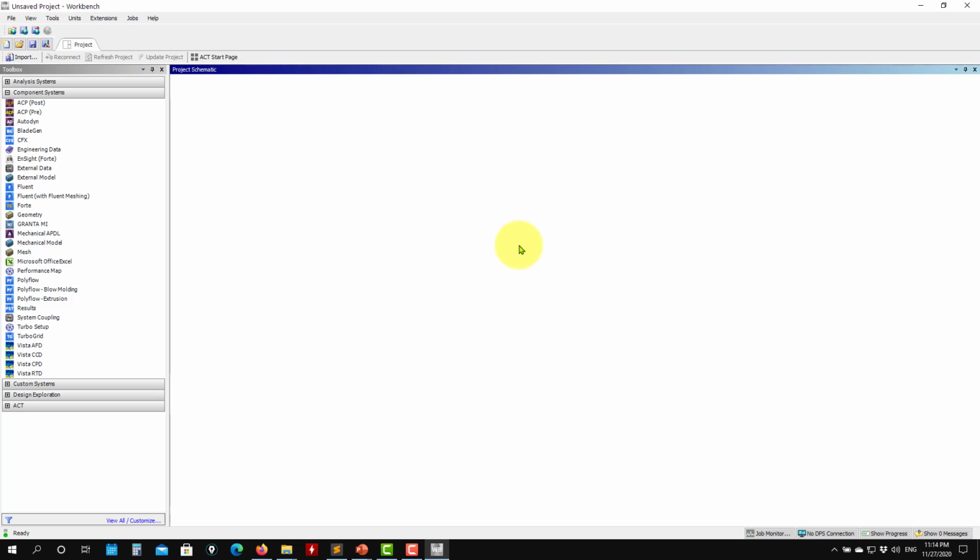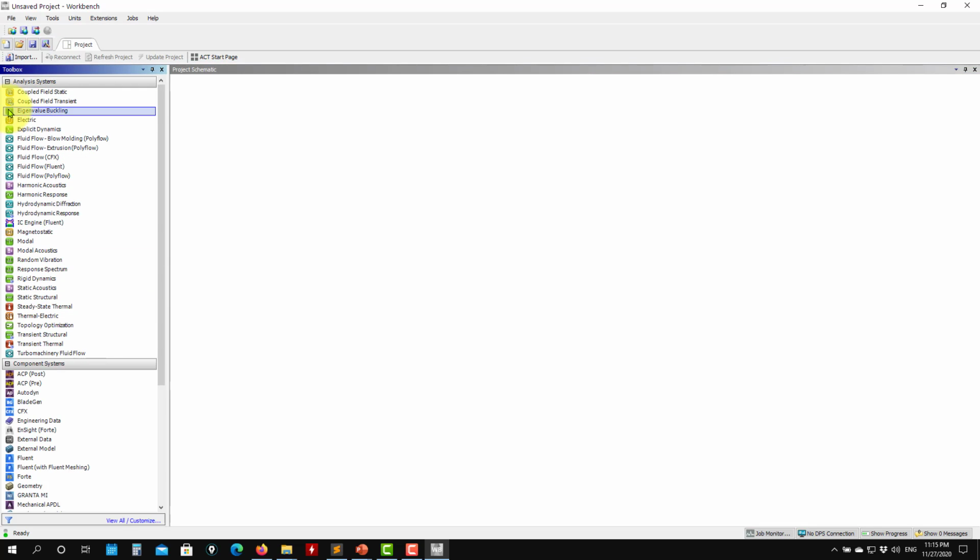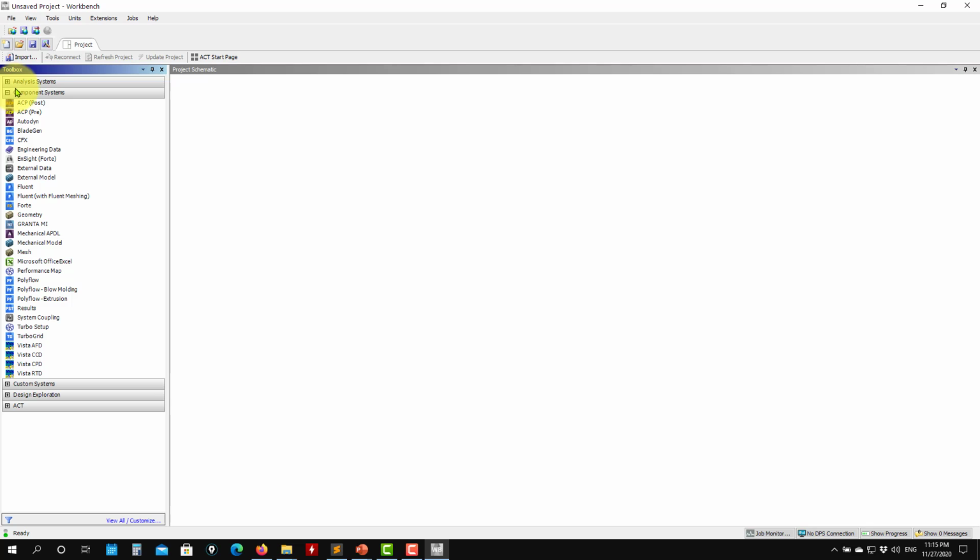So you're going to get this window. Here you have all the applications that come with Ansys. We're focusing on CFD here. You also have structural dynamics, a lot of stuff inside, but we want to focus on CFD. So the workflow in CFD is to generate a geometry, do a mesh, and then pass to the solver. Just to show you how things work, here it is drag and drop. So you identify what you want to do. See here that you have the geometry model.